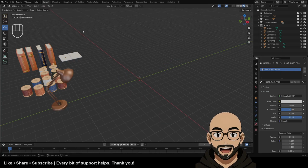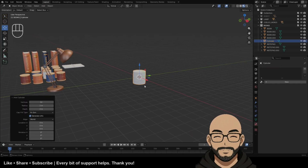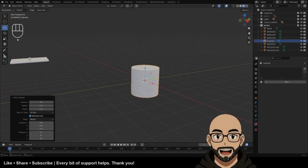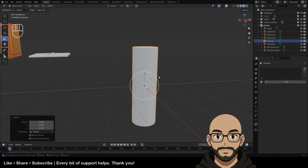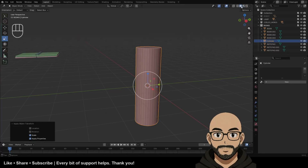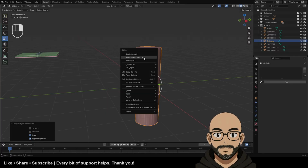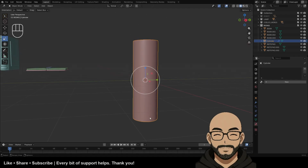All right, let's make a screwdriver. We're going to get a cylinder. This will be the handle. I'm going to scale this down, scale this up. Okay, Control A, apply scale. I'm going to go back into the other viewport shaded mode. Shade auto smooth.